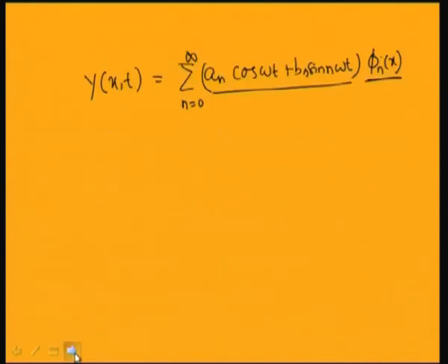In the series solution we have seen that we can approximate the function by truncating the infinite series to a finite number of terms, and the formulation and computation effort can also be reduced by truncating the series. We can do it in three different ways. The first way is to retain n natural modes only, consider them as the generalized coordinates, and compute n weighting functions to best fit the initial conditions or the forcing function.